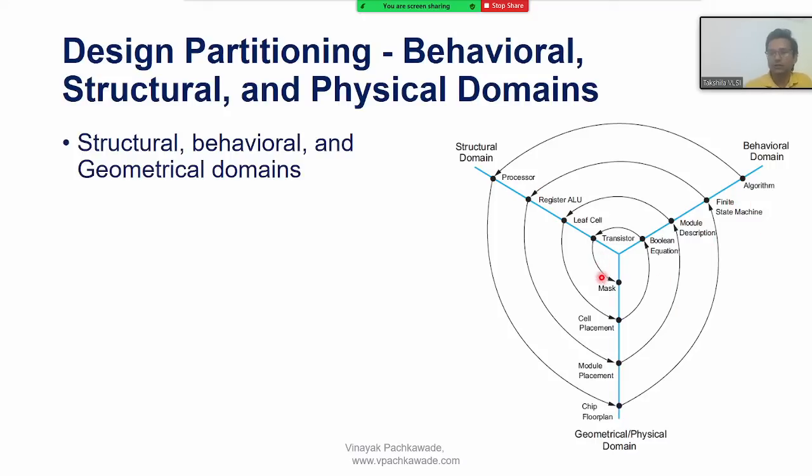In the structural domain, we start with the transistor. Transistors are used to build a unit cell. Let's say I use two transistors to make an inverter function, right? We know how to use the pull-up logic and pull-down logic. Using that inverter, I can implement NOR, NAND, multiplexer, latch, flip-flops.